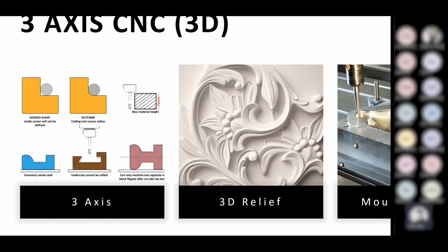So typically the way these would work anyway would be that you would have what we call a rough pass and a smoothing pass. So you would give the technicians your 3D file. They would then generate a rough pass across it first to remove the bulk of material, which would then hopefully go on to be recycled. And then they would swap out the mill bit for something thinner and a bit more detailed, and it would generate what's called a smoothing or finishing pass across the model. And that gets you these really nice smooth 3D reliefs like this one here, this white one.